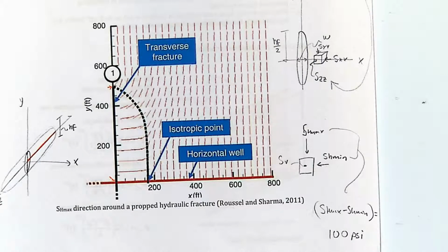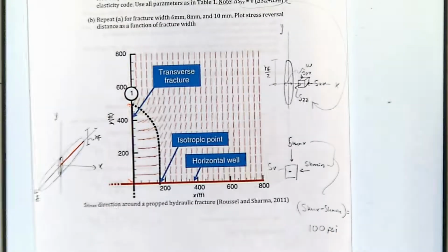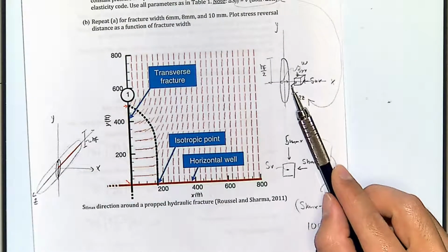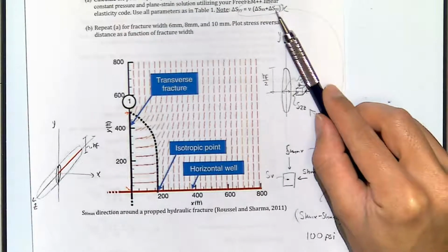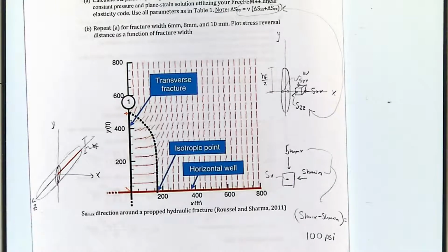But in order to make these computations accurate, because also you're going to have a Poisson effect, you need to compute the stresses in this direction, in that direction, multiply those variations times the Poisson ratio, and that's going to give you the variation in the third direction. And there you will be able to compare those two.